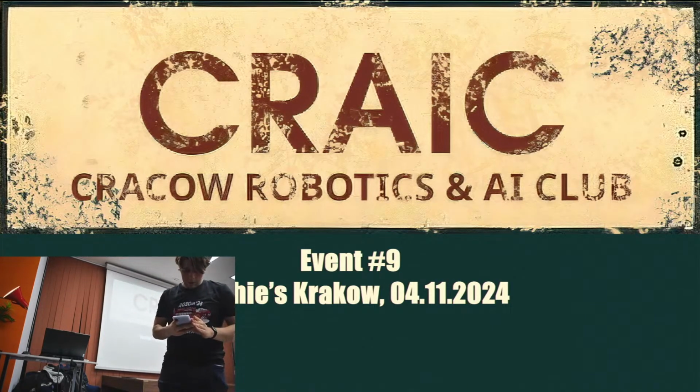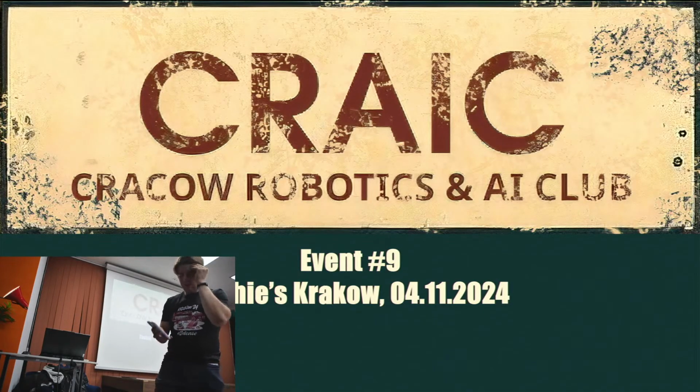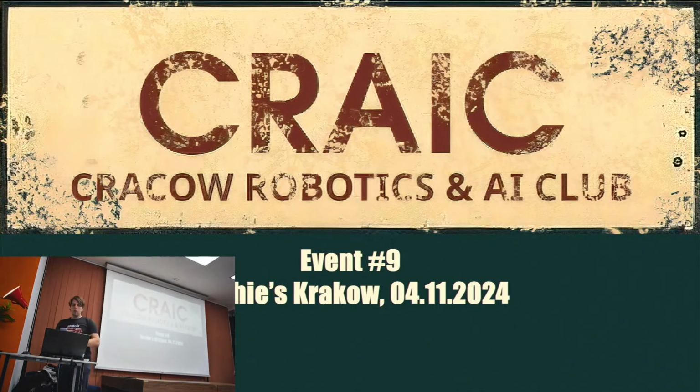Some way defined once you start your application, your custom ROS package, whatever you're trying to write. This has benefits and it also has some downsides. When you, for example, want to write a very simple application to acquire sensor data, and your sensor is publishing data in a certain way, for example, according to some specific ROS coordinate frame, you can have NED or ENU,